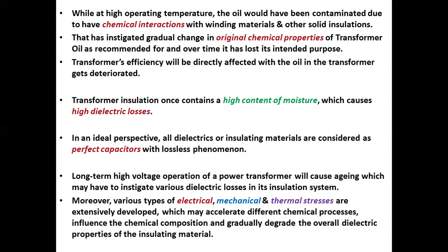Transformer insulation that contains a high content of moisture causes high dielectric losses. In an ideal perspective, all dielectrics or insulating materials are considered as perfect capacitors with lossless phenomenon.